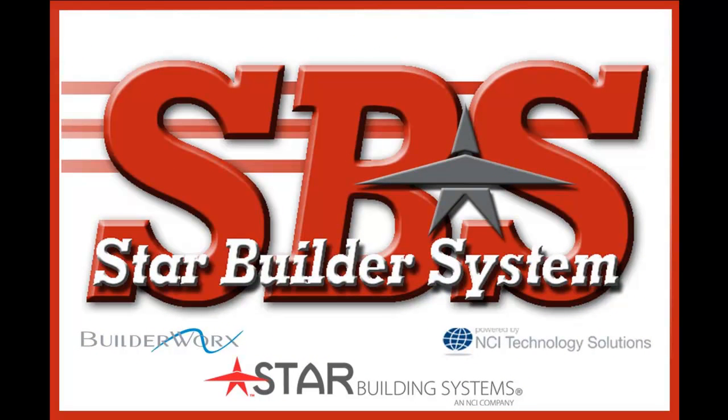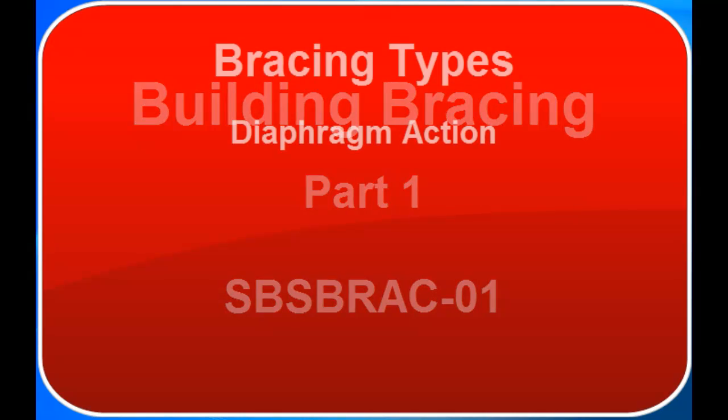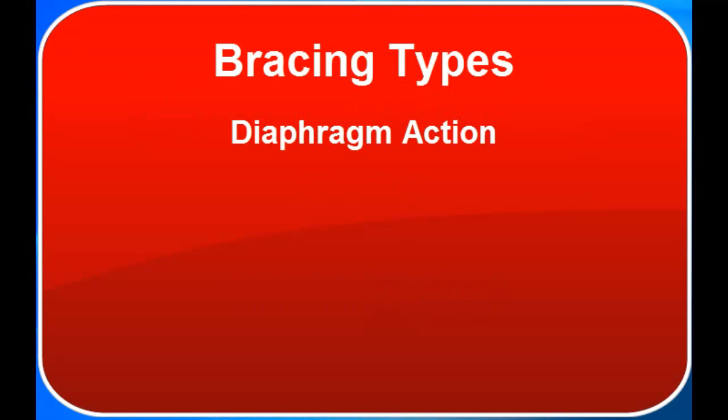Welcome to STAR's SBS tutorial on building bracing. There are multiple types of bracing that can be utilized throughout the building with various configurations. The most cost-effective means of bracing a building is diaphragm action using the panels, i.e. PBR, as a shear panel.